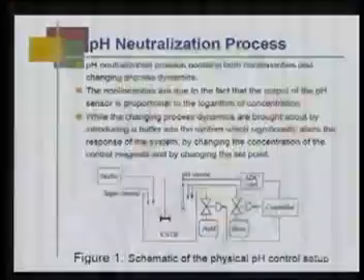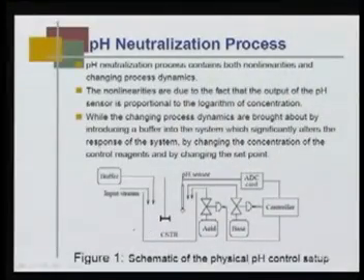It may seem that this is a fairly simple process, but actually pH control of a reagent or reactant, whatever you say, is not an easy task because of nonlinearity. The nonlinearity is that pH is nonlinearly related to the concentration of the liquid.